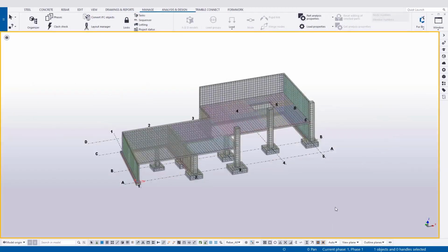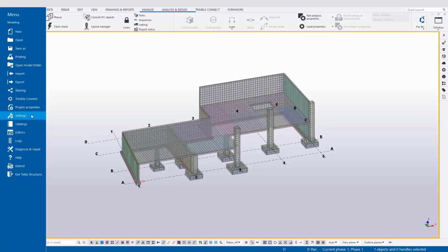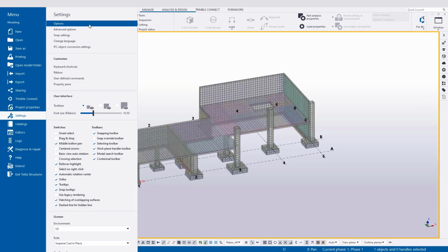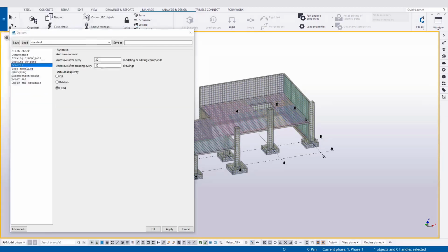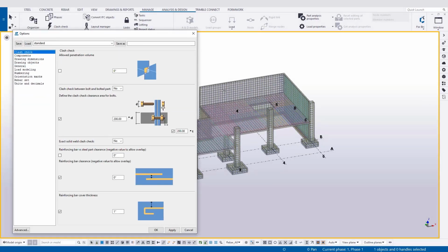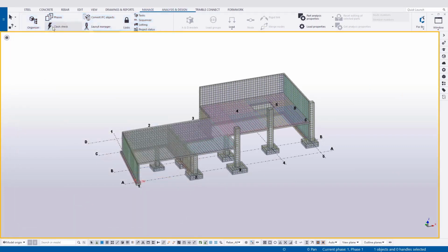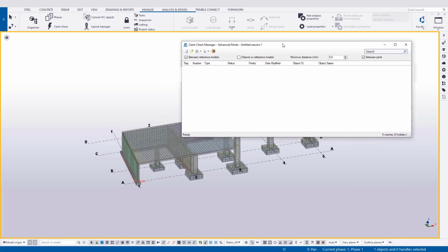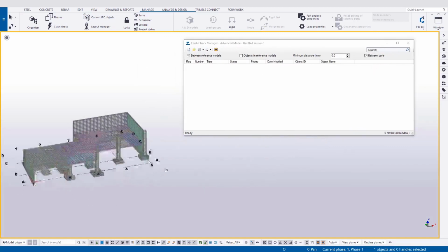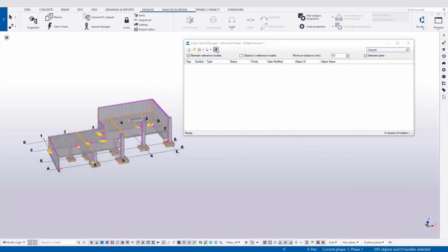The other end of constructability review would fall in a more traditional clash detection. This allows users to identify potential issues based on clearances provided in the model's options. Users can select the model and perform the clash detection and then review the results. You need to choose to either ignore, group, or resolve issues presented in the report. Reports can be saved so they can be worked and reviewed over time.